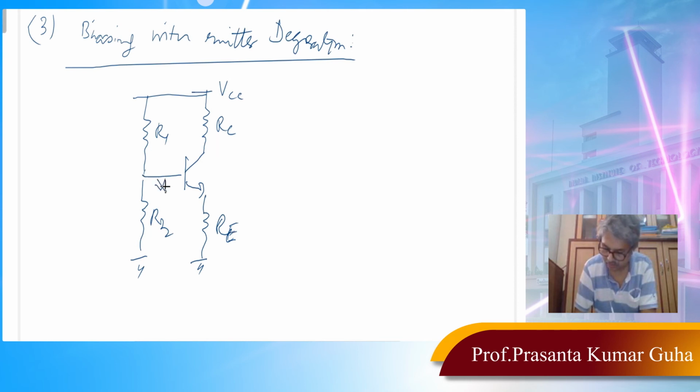Okay, again, if you do that, the beauty of the circuit is if there is any change in Vx, maybe because of variation of R2, again, you can analyze this circuit as we have discussed already by assuming that the current here is much greater than IB, or you can use V Thevenin and R Thevenin and find out the expression. Okay, but intuitively we can say that if there is any change in Vx, because of change in R2, that change in Vx will be absorbed across RE.